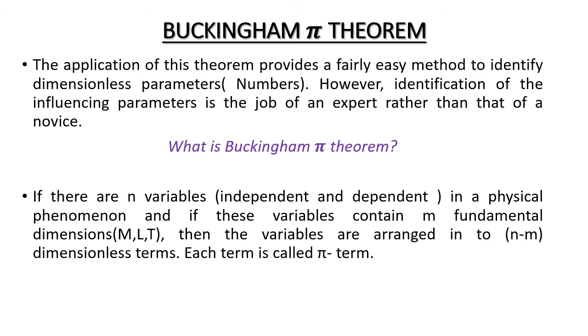In mechanical problems we mostly come across three fundamental dimensions, mass, length and time, and sometimes two, like the last problem. Then the variables are arranged into n minus m dimensionless terms.